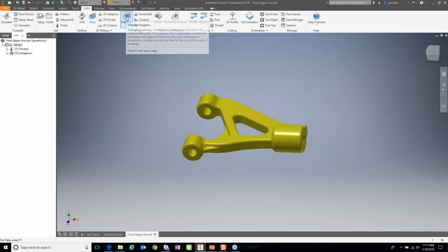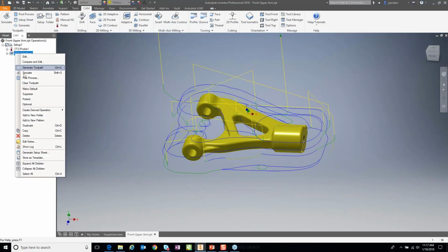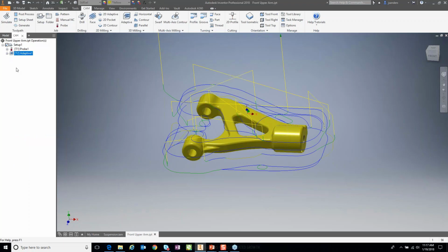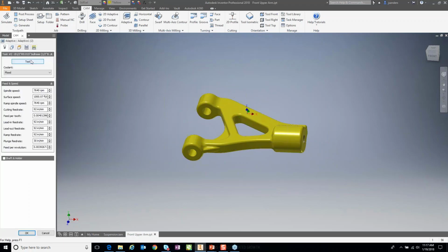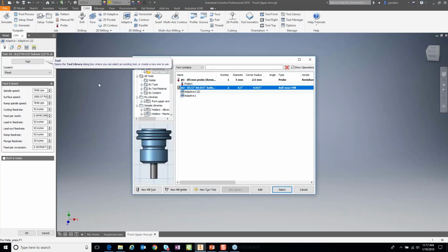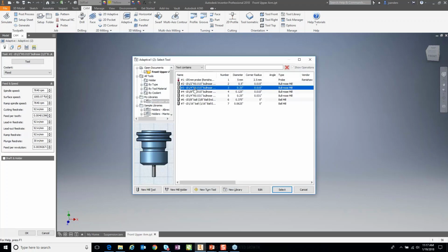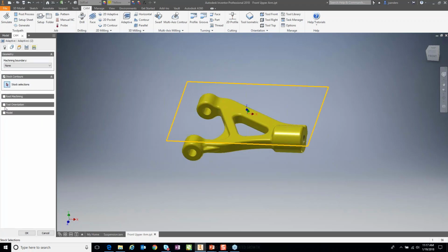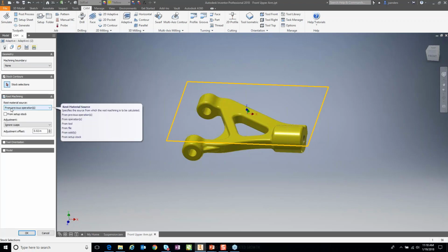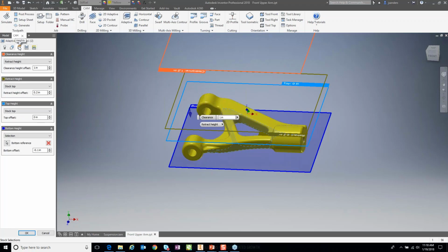Instead of making another adaptive cut and putting in similar parameters, it would probably be fastest to just copy the tool path that we have here and then reuse that by pasting it in and modifying a few parameters. Now, after I've modified it, I've edited it. We mentioned that all of the tool path is editable, and we're doing that here. I'm going to switch out and use a smaller cutter. Let's go in with a 1/4-inch roughing tool now. Again, the cutting data is updated as needed. For the main directions of what to do, I'm going to have this do rest machining, or machine what is left over from the previous operation. Work heights are all the same.